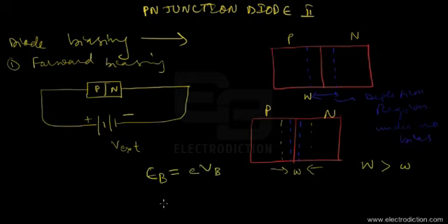That is, they gain an energy equal to the barrier energy, and with that they surmount the voltage barrier and cross over the P-N junction, thereby leading to a net flow of electric current through the P-N junction from the P to the N side. So there it goes.